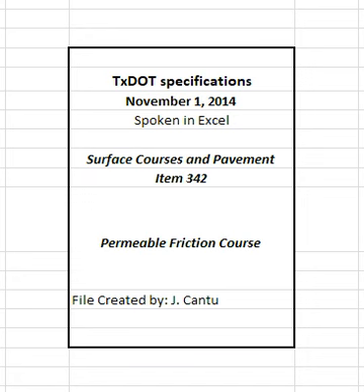Paver operations, for example operation of wings, height of mixture in auger chamber, to avoid physical and thermal segregation and other surface irregularities, and procedures to construct quality longitudinal and transverse joints.